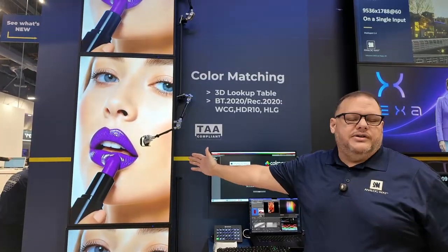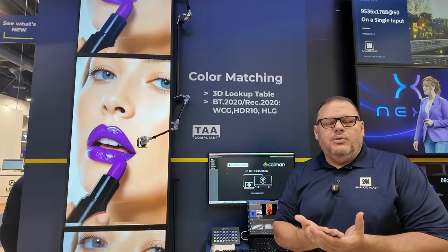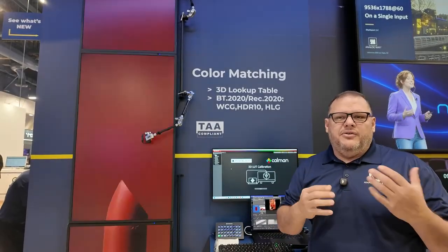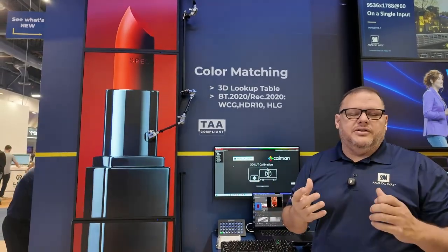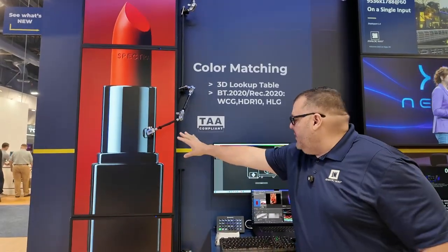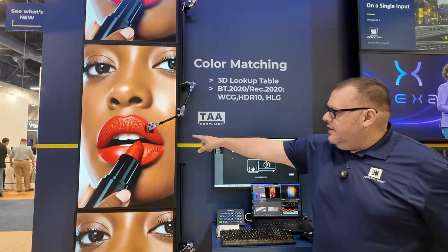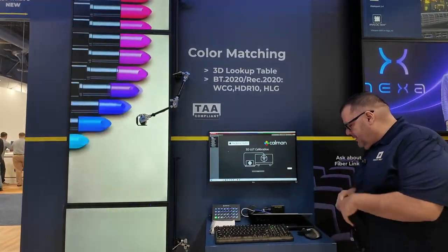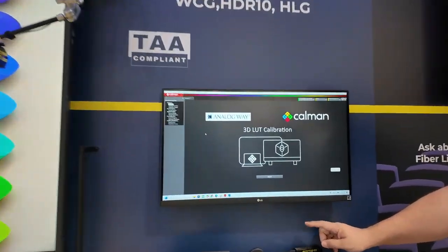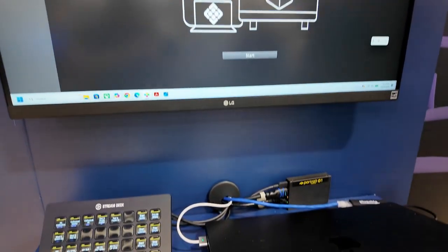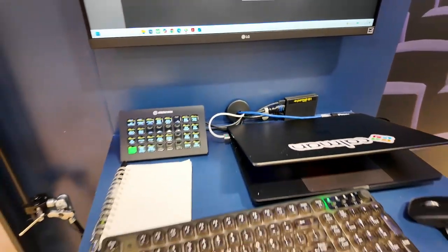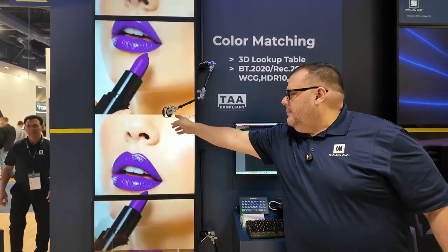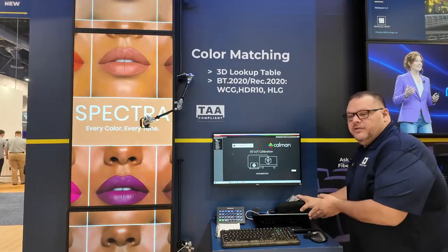What we wanted to do is, our director told us he wanted them at 5,500, which is usually what we want in video, in the 5,500 or 5,000 range. It depends on the production. So immediately I ran this workflow. I created a LUT with our colorimeter, and I have a pattern generator back here, a Portrait G1. The pattern generator goes through the switcher out to the monitor, and then we read it with our colorimeter, and that's what builds the LUT.